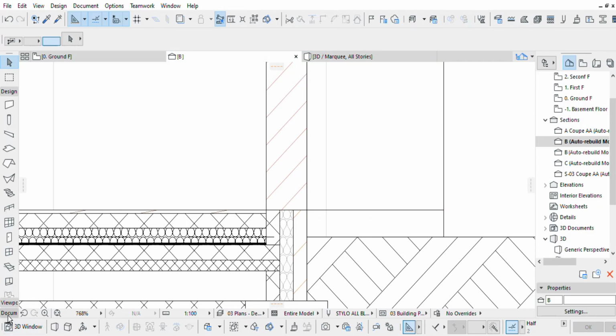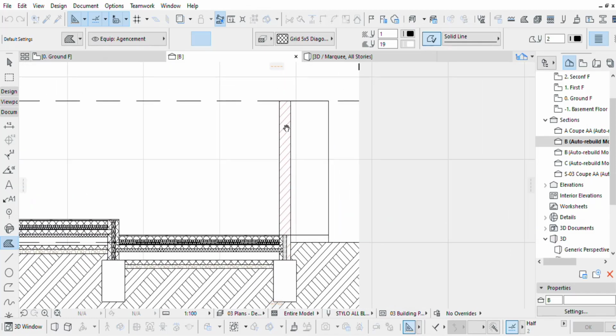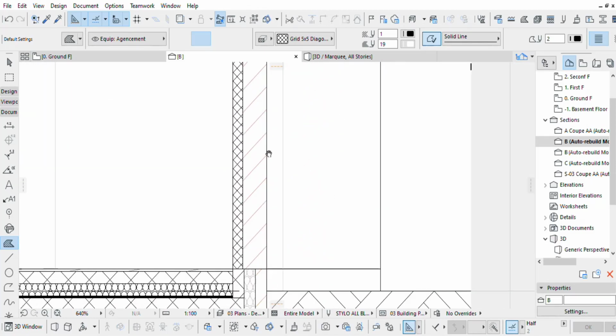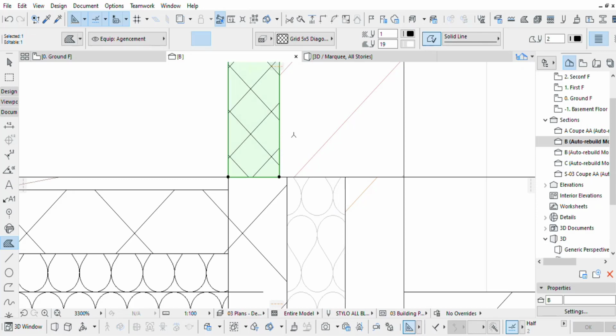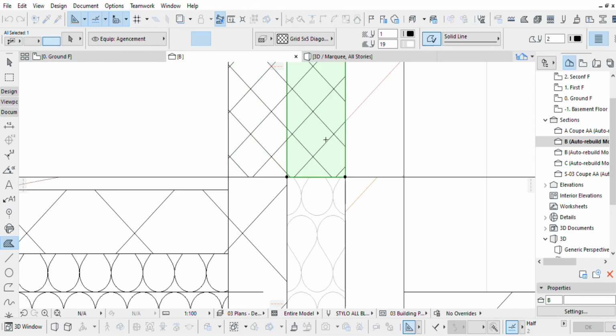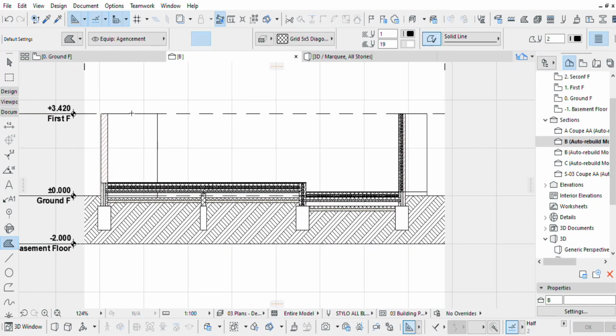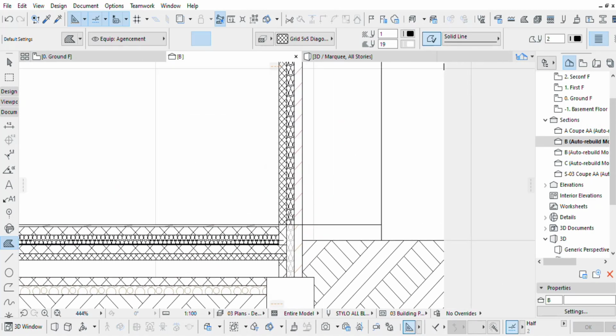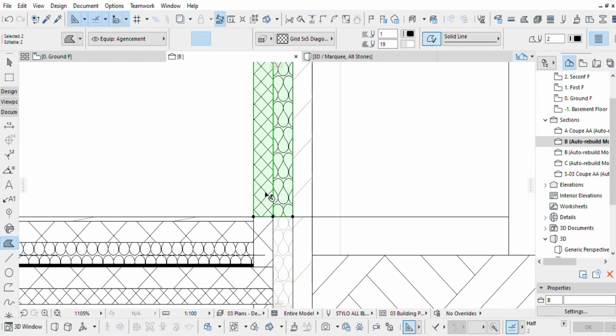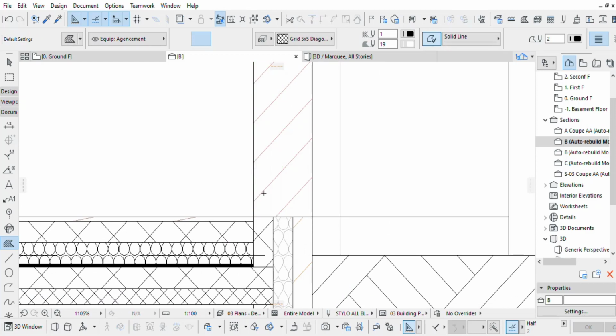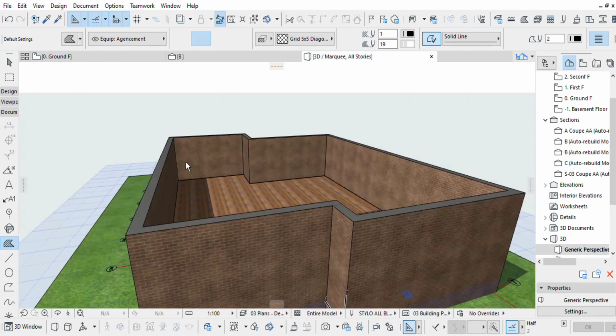Obviously, if you want a quick way to fix that, you can still use your fill tool and you can create that manually, as you can see. Here we go, and then you pick another surface which is insulation, maybe like that, and here we go. But when you go to the other side, you have to do it unfortunately manually for each one of them, and that's where the second option is here for, the one that we spoke about earlier in the beginning of the tutorial, our composite wall.